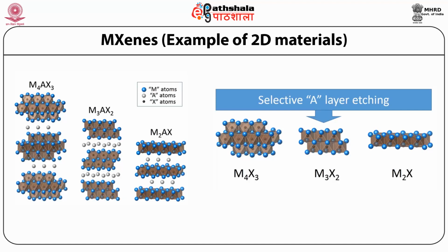The MXene Ti4N3, currently the only nitride MXene that has been reported to be synthesized, is prepared by a different procedure than those used for carbide MXenes. To synthesize Ti4N3, the MAX phase Ti4AlN3 is mixed with a molten eutectic fluoride salt mixture of lithium fluoride, sodium fluoride, and potassium fluoride, and treated at elevated temperature.